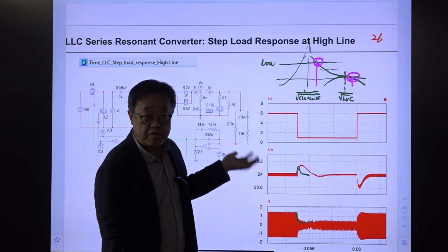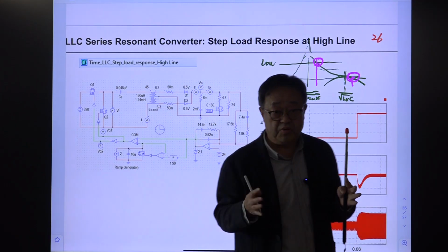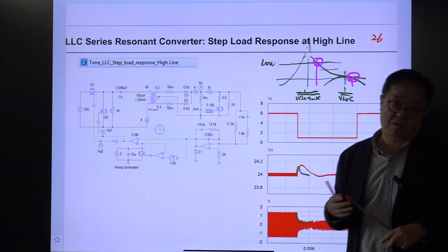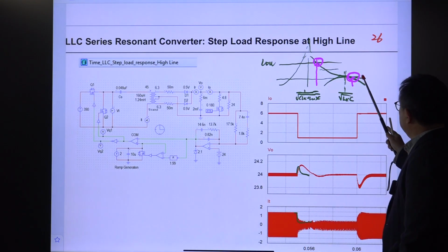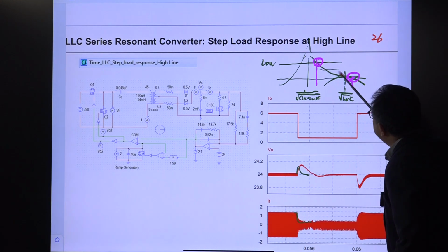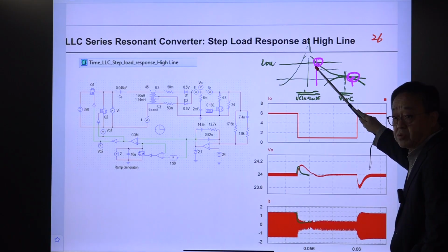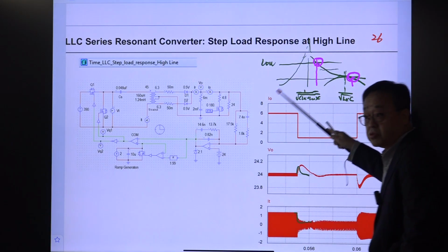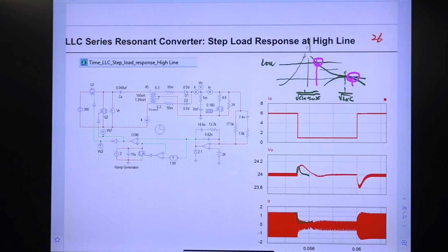Okay, previously we saw that, and that design was the best design for the given condition. If you take another approach, you design your controller here, and you move to this place, you climb up to this operational point, the converter becomes unstable. Definitely, it becomes unstable. All right. So that is the problem of voltage mode control. That was the problem the industry was suffering from.